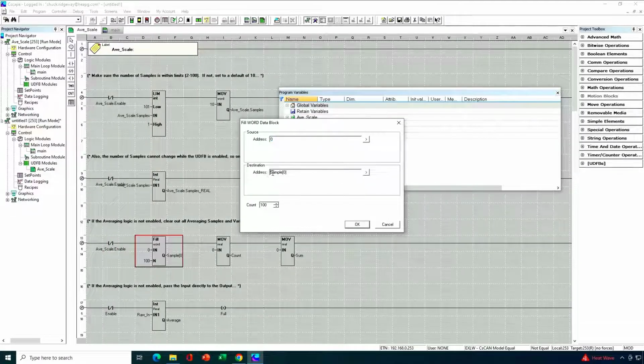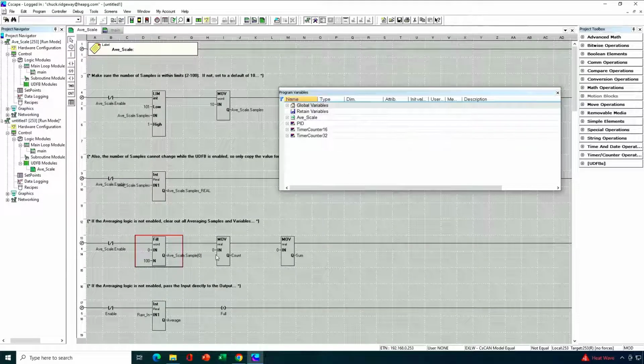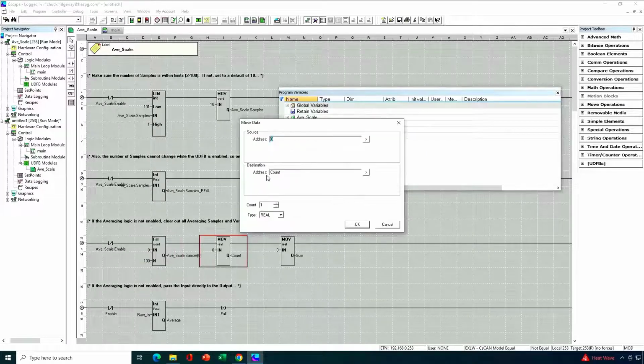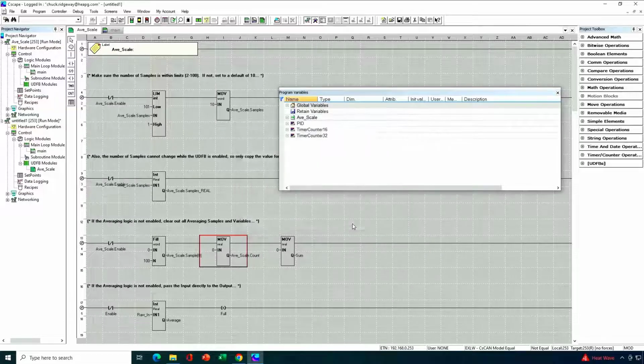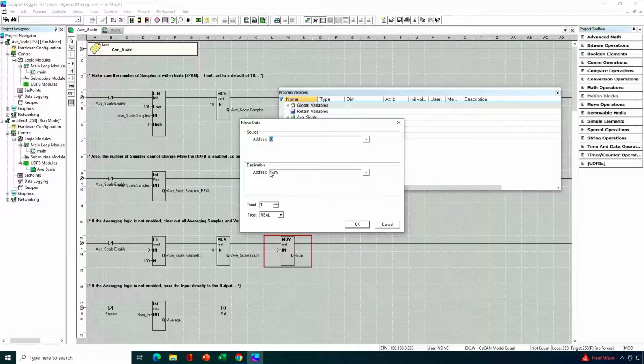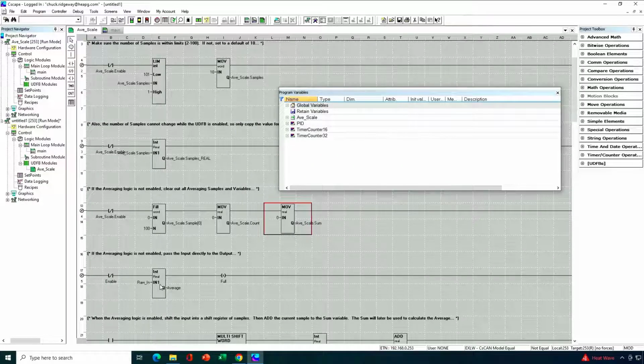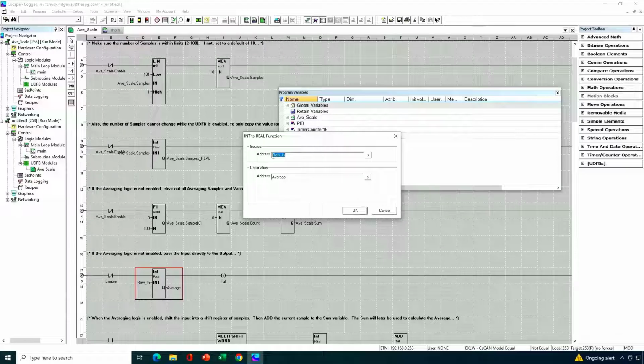One thing I do want to mention is this. An advantage of creating a brand new program to use when you're doing the UDFB is that all these variables I'm replacing technically aren't even on the variable list in my program variable window for this project. So if I forget, as I'm editing, to put a prefix in for one of the variables, I'm going to get prompted and it's going to say, hey, do you want to create a new variable? Because it's going to see the one that I forgot to replace as a new variable.